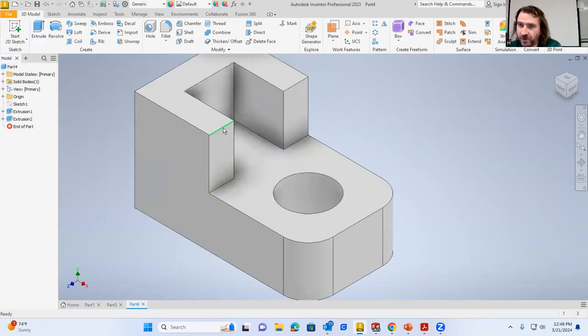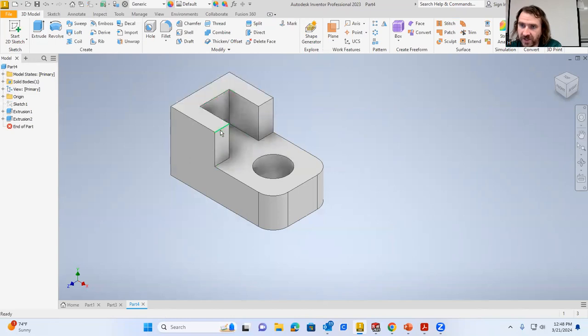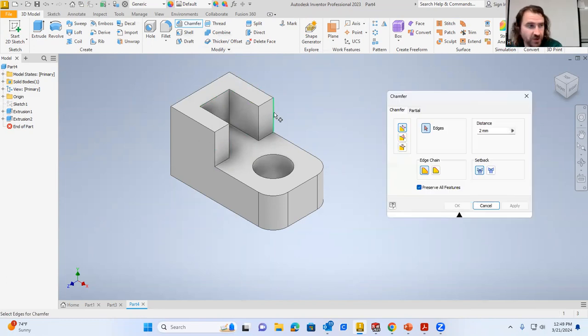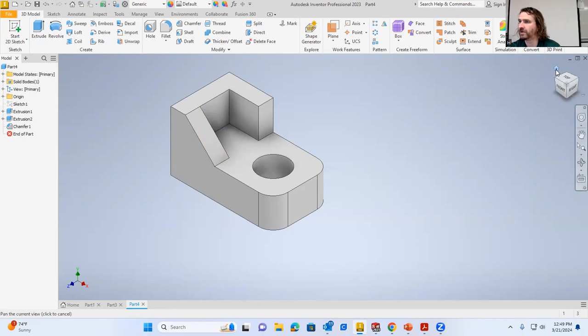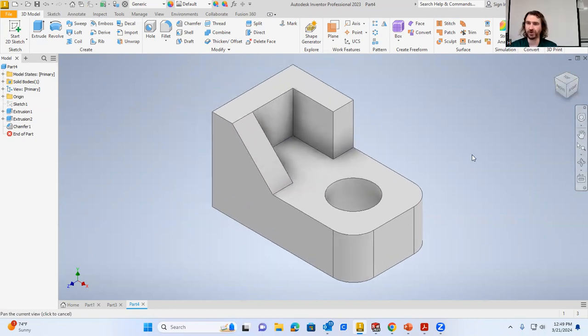Now we need to chamfer this edge here. Again, this edge here. So we want to chamfer this. And in the chamfer window, we're just given the amount horizontally in this direction of 20. But in this instance, the chamfer is equal in both directions. So it's equal distance of 20, which is our first chamfer option here, distance 20. And so it's going 20 horizontally, 20 vertically, chamfering off that corner. That's it. That is lesson 2.